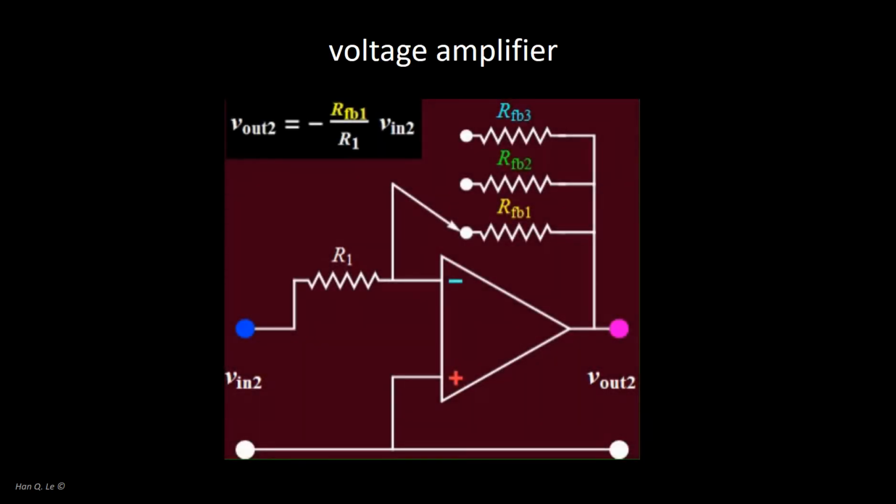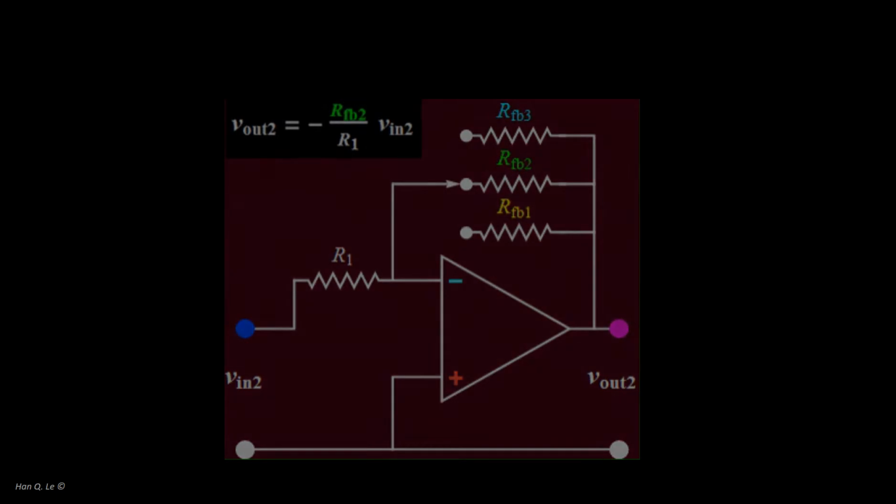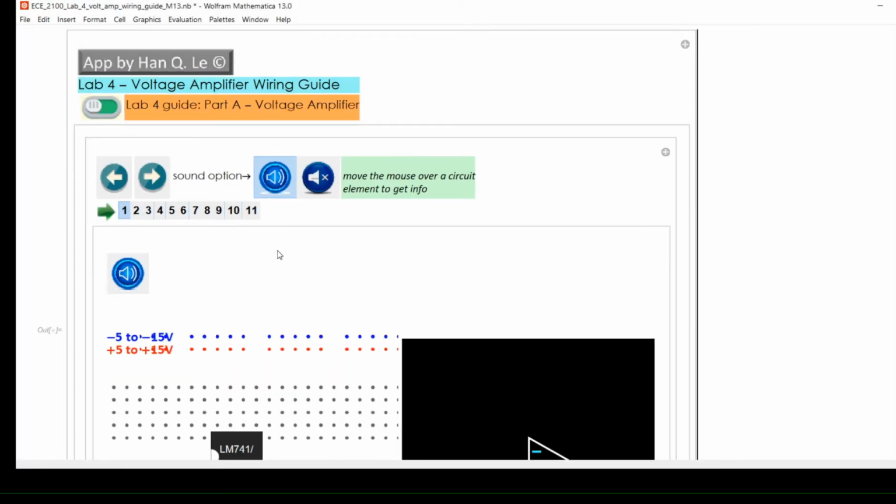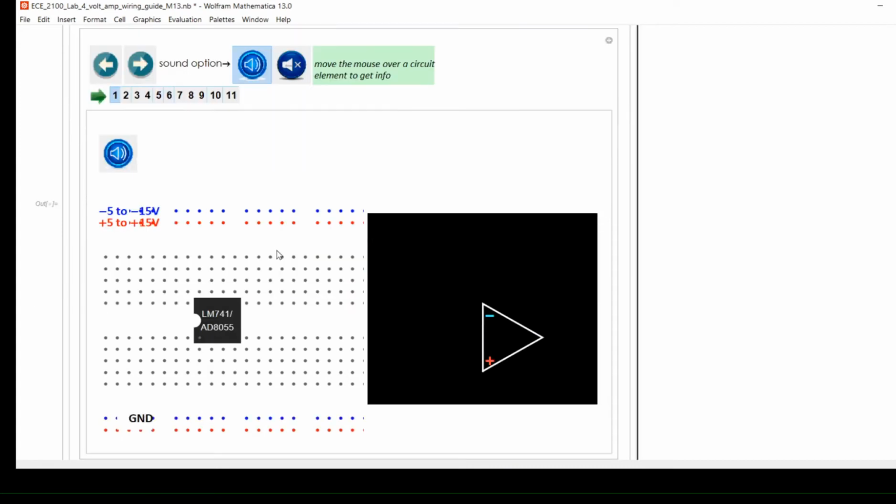This is the circuit schematic, showing 3 selectable feedback resistors for 3 gain values. Gently rock back and forth, side to side, to insert the op-amp onto the breadboard. Avoid bending the pins.